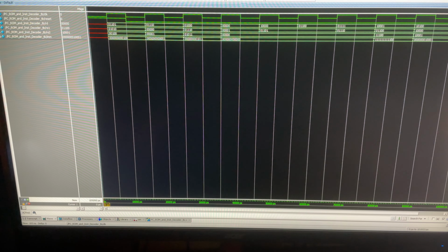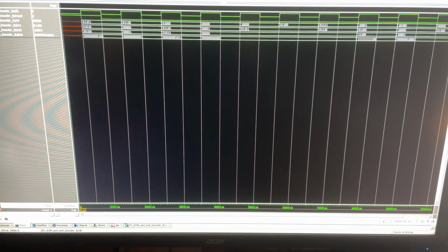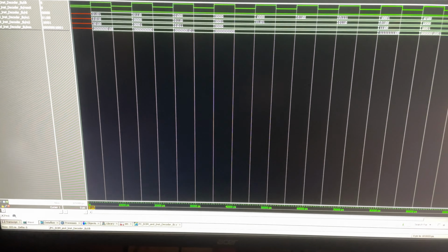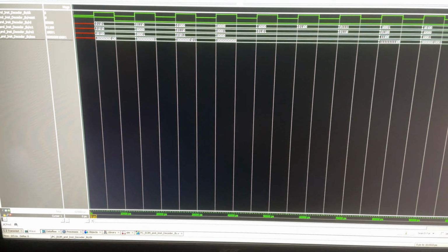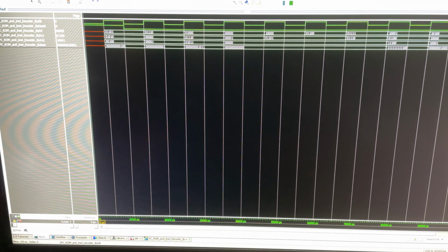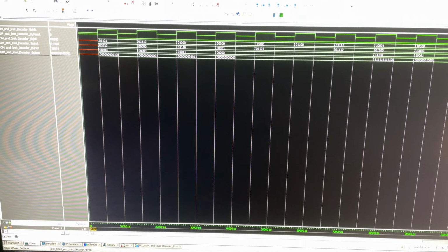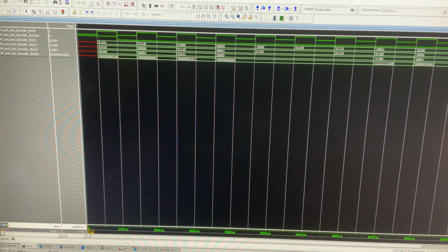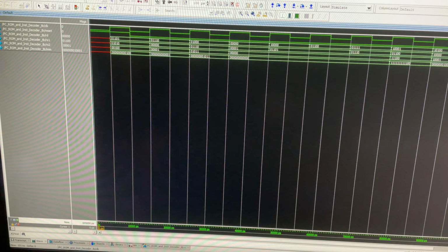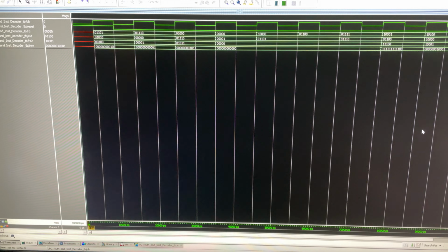So to explain this top level design, this ModelSim is going to show the functionality of our program counter along with the instruction decoder, and it's going to be assisted by the ROM and the +4 adder. The program counter and the +4 adder are going to cycle through the instructions within the different addresses of the RAM by adding 4 to each additional address. Meanwhile, the ROM has the addresses of R and I type instructions. The final component, which is the decoder, is going to take these instructions, and it's responsible for giving us our main outputs that we're viewing here.